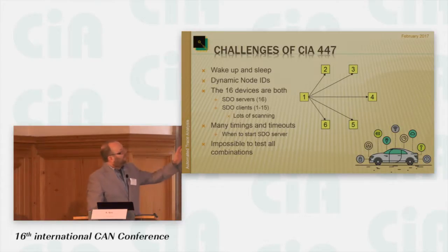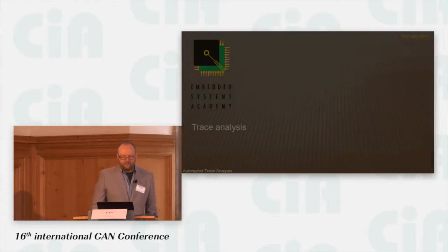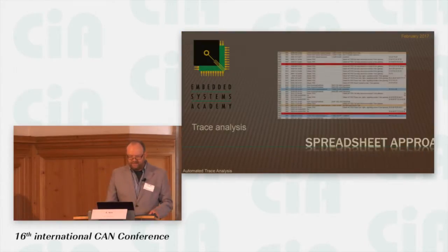So where we had the usual CANopen setup with one master or manager, one SDO client communicating with all the other nodes, here every node can send individual SDO requests to all the others at the same time.